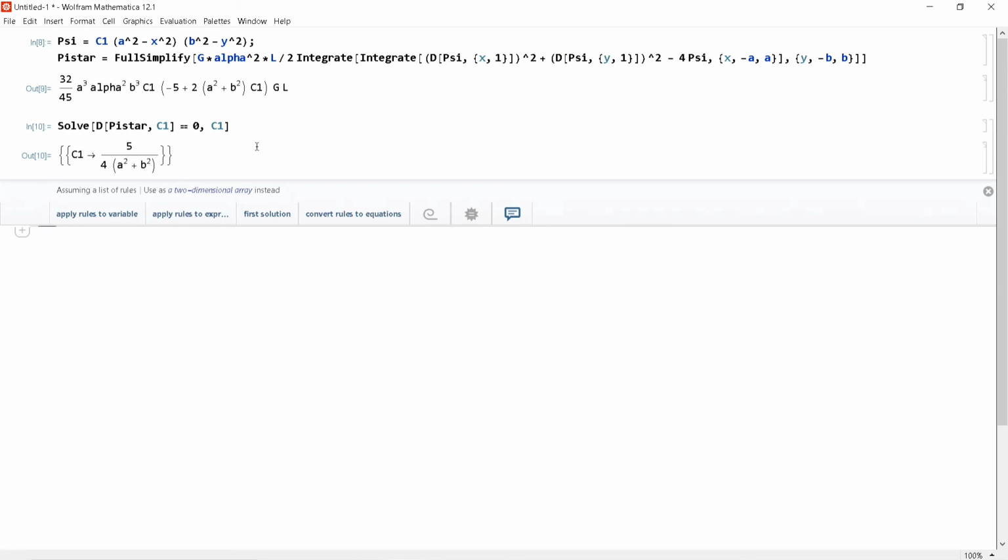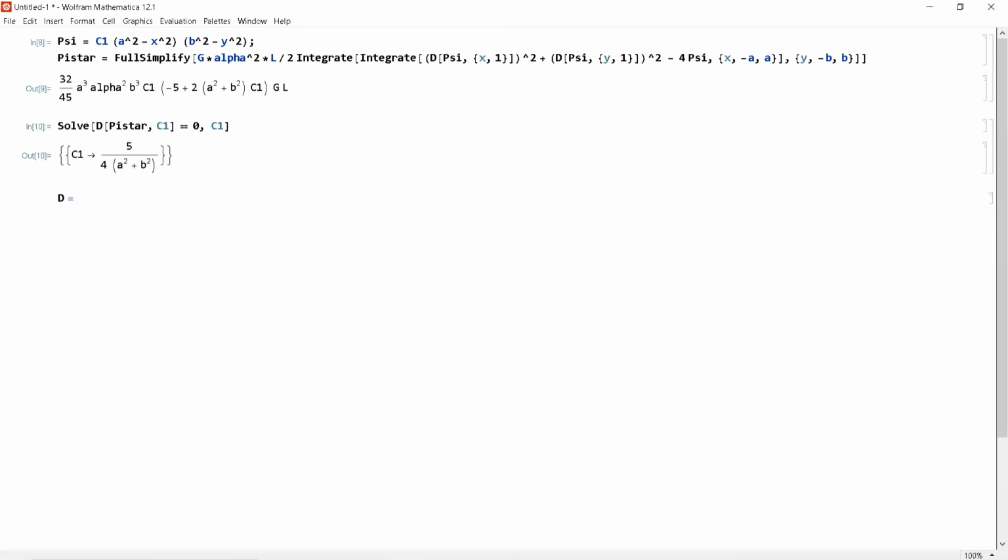And now I'm ready to take D, calculate, say, the torsional rigidity, which is M divided by alpha. I can calculate M divided by alpha, or I can calculate the moment as well, if you want. Regardless, I can just calculate the moment: the moment equals twice G times alpha.